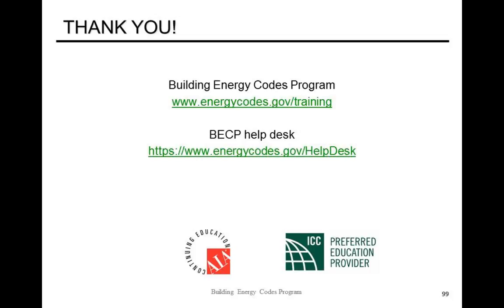Now, if the question is about how they are handled between the two models, the baseline and the proposed building, in simulation, in general, they're held the same if they're unregulated, except as I discussed in the previous question, if you can demonstrate to the rating authority that you've gone beyond standard practice, then they give you permission to model them differently for beyond code program credit. Hopefully I covered the question. I'm not positive that was it, but I think so. It was a little generic.